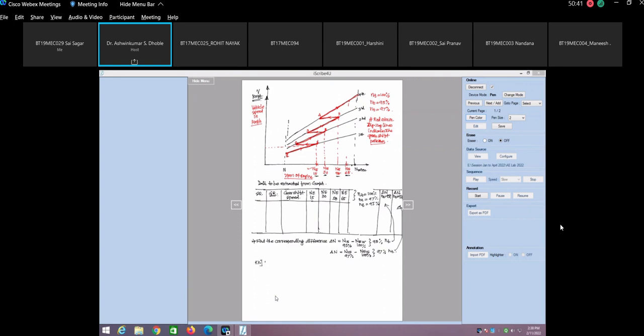okay. So when transmission efficiency was 100%, for 15 kilometer per hour, let us say the engine RPM used to be 3000 RPM. Okay, then when I change transmission efficiency to 97%, then for 15 kilometer per hour my engine RPM naturally will be more than 3000.